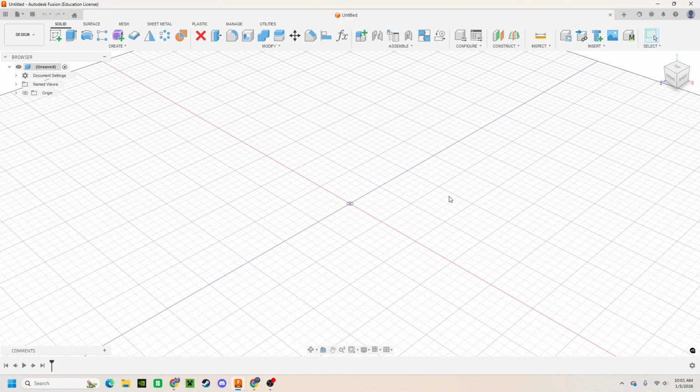We are going to learn one of the most difficult concepts in Fusion 360. These are constraints. Learning and understanding constraints can be very difficult and takes a lot of time, but once you master them, you can truly begin to model successfully within Fusion. Constraints are essentially modifiers within sketches that define three things within sketches: position, angle, and length. Understanding how to define every part of a sketch's position, angle, and length is critical to modeling.